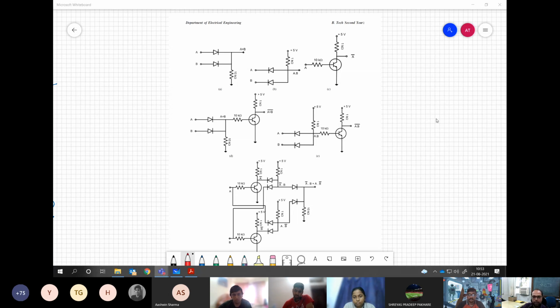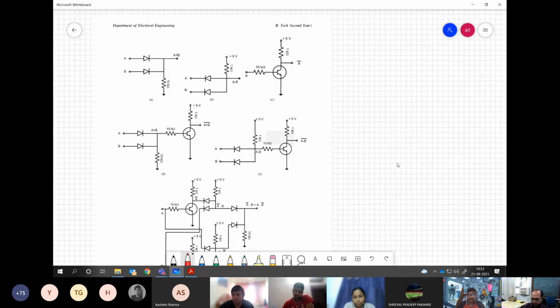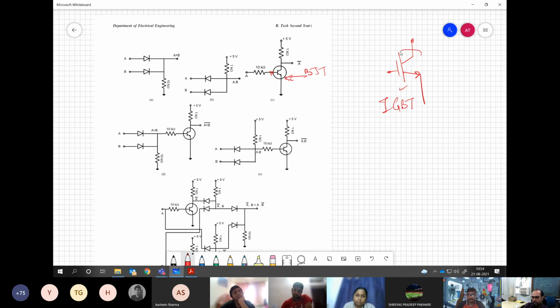The basic difference from what is given in this circuit and what you are doing in Simulink is this device. We are not using BJT, but we are using another equivalent device which is voltage driven, that is called IGBT. The only difference between this device and the BJT is that BJT is a current driven device. You have to give enough current to maintain the biasing and all, that means the cutoff and saturation. Here, the same is ensured through voltage given at this terminal.